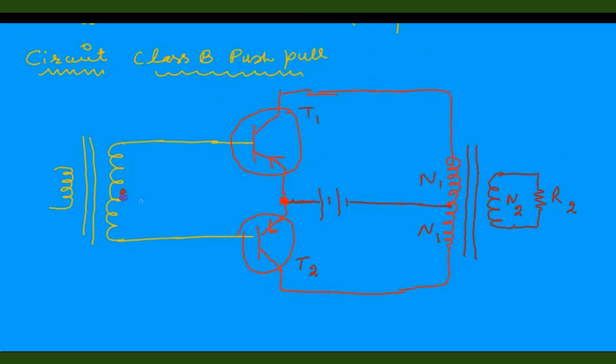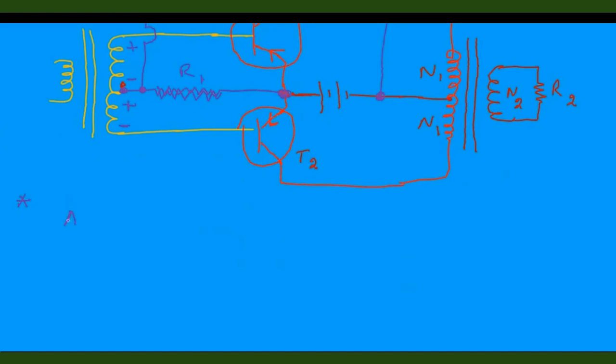Now this is the circuit diagram for the class B amplifier. Here we are using the PNP transistor. This is very important. Of course, you can make the connection with NPN also, but battery placing should be proper, as shown in the figure. There are the resistors R2, R1 for the biasing. The biasing is given so that some very small current flows in the absence of the signal.